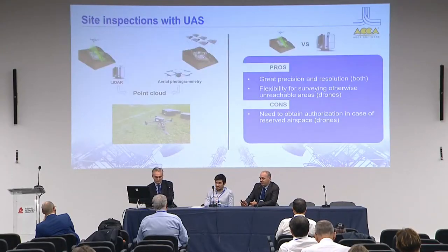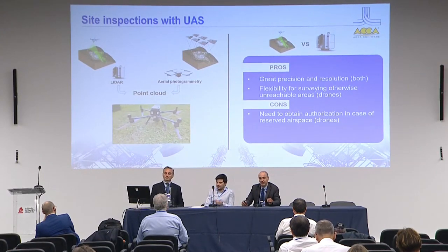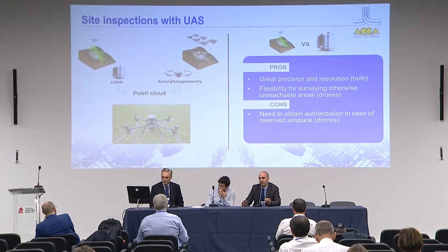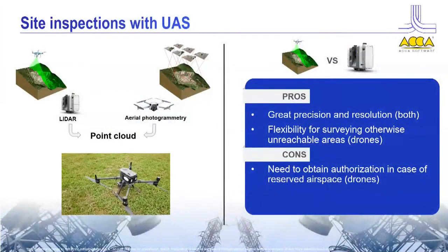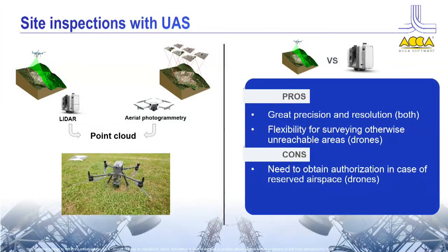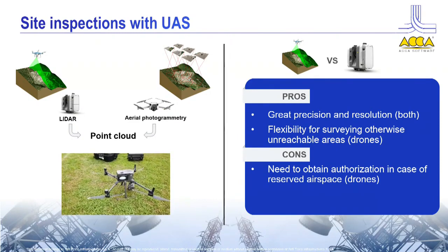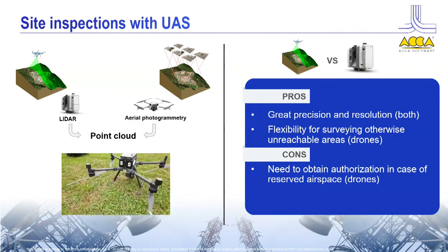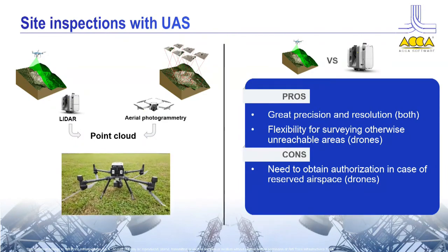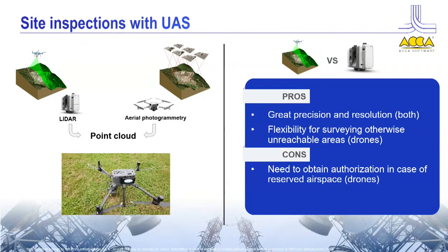Okay, I'll try to describe the possible workflow we designed together with Sirti for the building of this information model. We investigated various technologies for the surveying. The final result, in any case, is made up of a point cloud. This point cloud may be produced with aerial photogrammetry or with LiDAR devices, both from the ground or installed on drones.